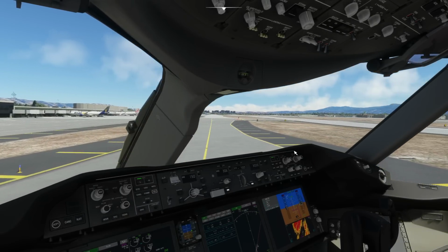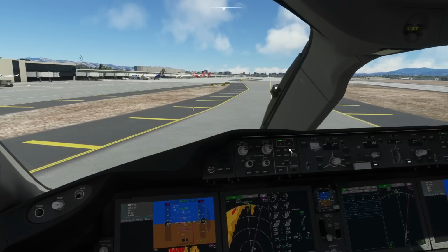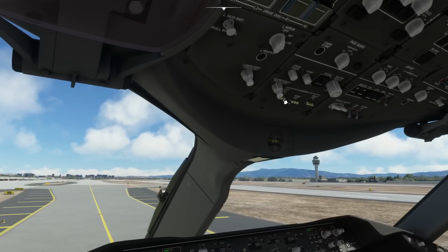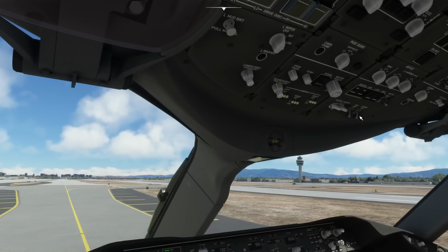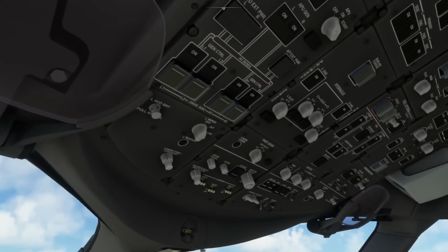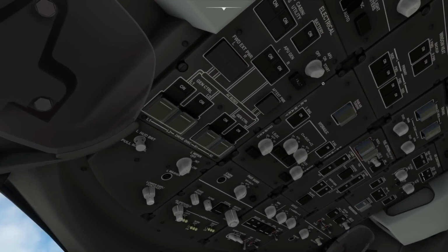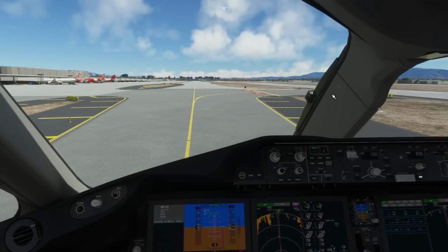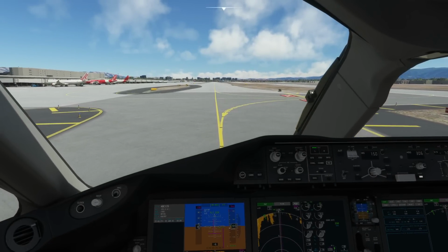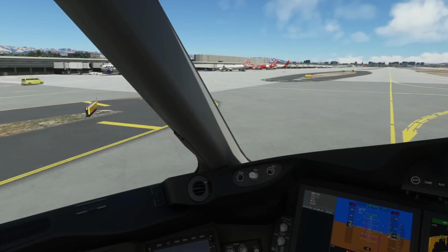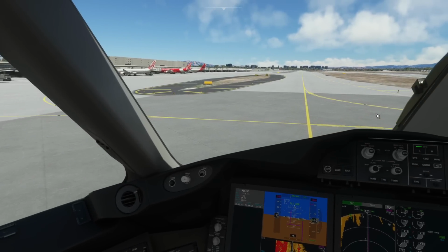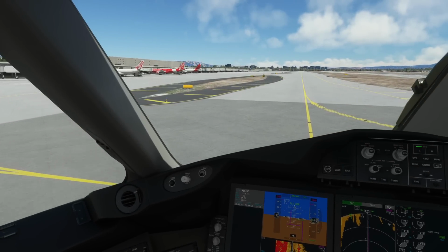So obviously, in common with lots of other aircraft, on the way in you're going to turn off the landing lights, you're going to turn off the strobes, you're going to switch on the APU very probably, so you'll start it back up again. And then by the time you get to a gate, if you don't have external power, you can rely on your APU once you've shut the engines down.